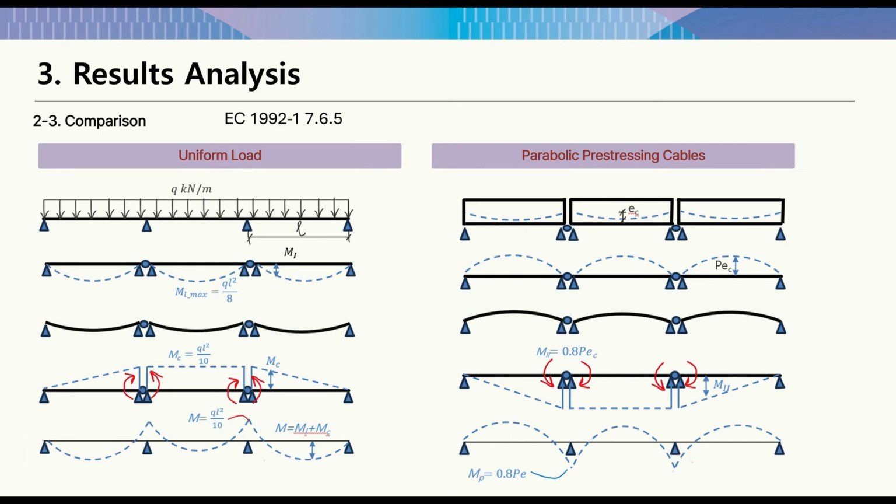Here is a comparison for simplicity and clarity. Free bending moments and continuity moments caused by external loads are connected by the laws of statics, and therefore are considered together as a bending moment, without separating the moment of static indeterminacy and the moment from the load in a statically determined structure. But it is convenient to separate them in pre-stressing, in particular for the ultimate limit state resistance verification. See Eurocode